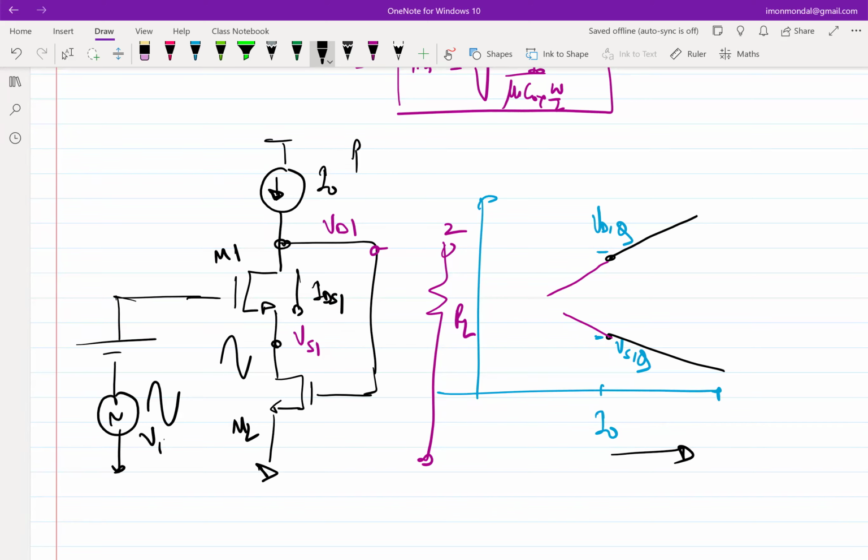But when you want to ensure that we get a common source type of operation going, then this is not particularly good. We want the incremental current to change. Correct? So essentially we don't want the quiescent current to be dependent on all those variables, but we want the incremental current to be dependent on the input, not the quiescent current, right? So now, can you suggest a solution?